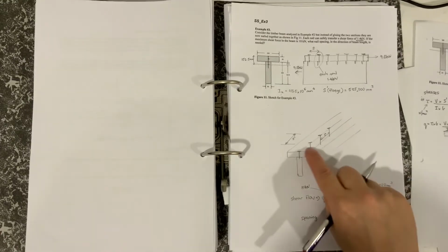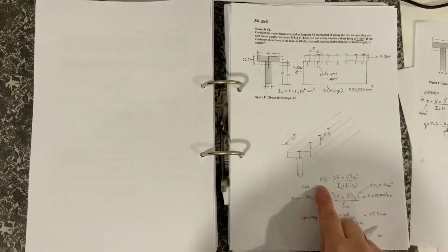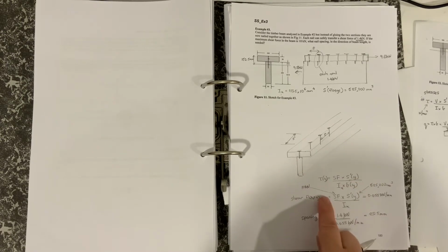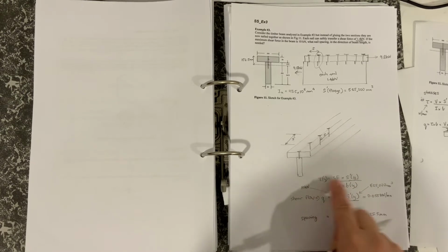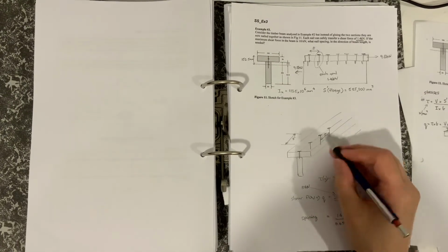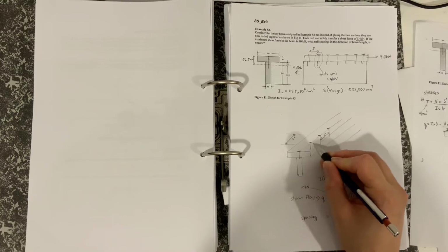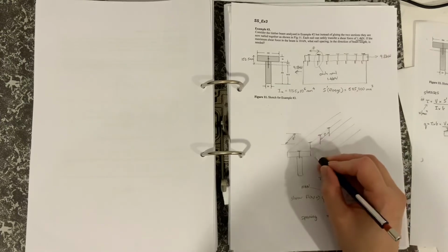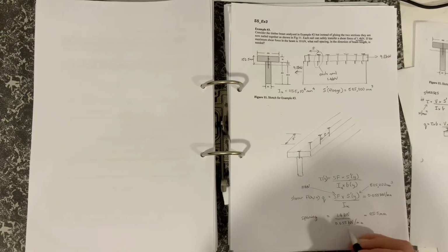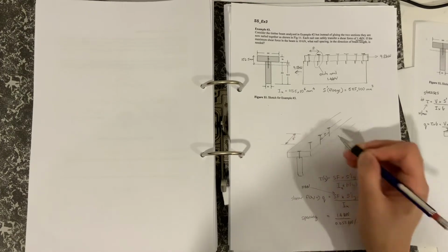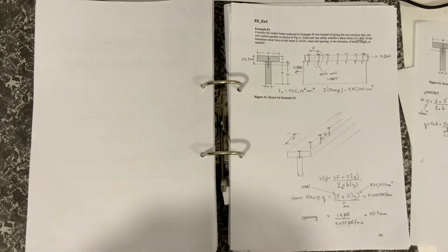So you can see that we don't even need to bother about the shear stress. Instead of thinking in terms of a stress, we think of a flow going through there per millimeter, the millimeter being in that direction there. Just divide the 1.4, which is the strength of each nail, by the shear flow, which is per millimeter, and you would get the required spacing of each nail.